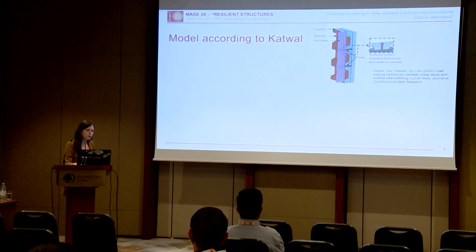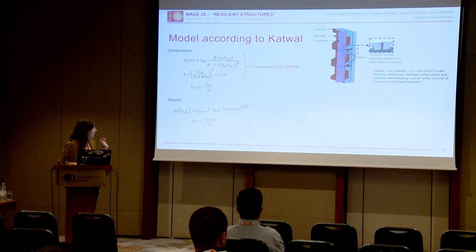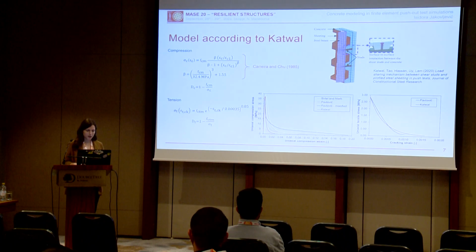And the third model, according to Cutwell, was also used for modeling the behavior of headed studs in profiled steel sheeting. For compression, he used only one equation that was previously proposed by those two authors, and for tension, he used an exponential function. When we compare it, that is how this model looks.